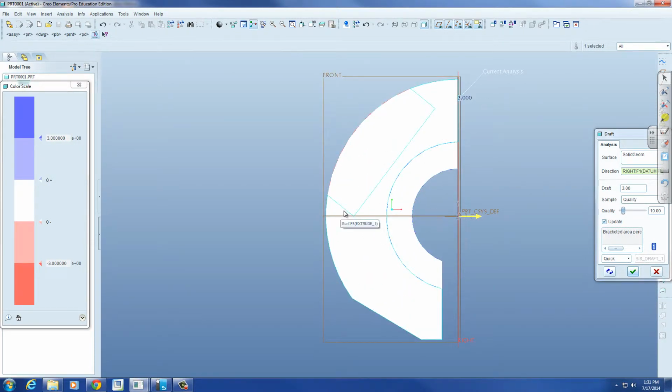If I were pulling it this way, I could pull this, but if I had steel come down and shut off, I'm going to have a split draft right here. So if I tried to pull all this from this side, I would be obstructed by this. If I tried to pull all this from this side, I might have to split this about some parting line that we may create. So that's the first time that we're going to be doing that.